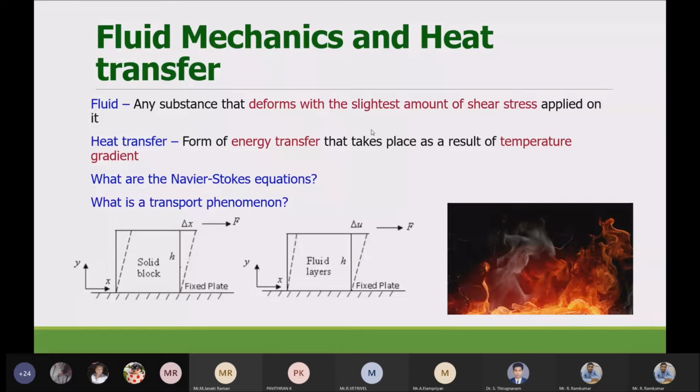However, there are a lot of different forces. A fluid obviously has viscosity, so it will have viscous forces, and if it is under the action of gravity, it will have gravity body forces and a lot of other forces and different sources of acceleration on the right hand side. F is equal to ma is what I said. So F is different types of forces and a is different types of acceleration. So clubbing all of these together is what CFD is about. This basic equation is what is being used to solve computational fluid dynamics problems.